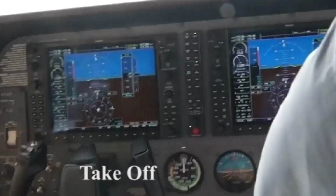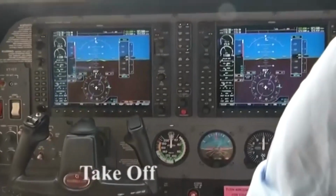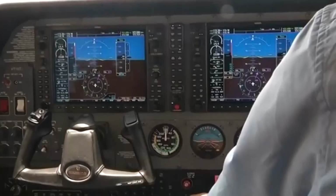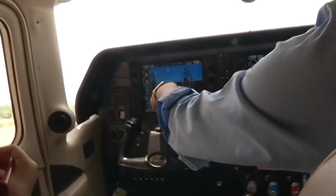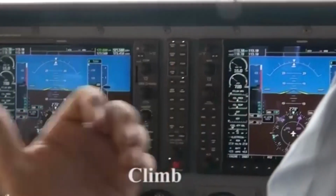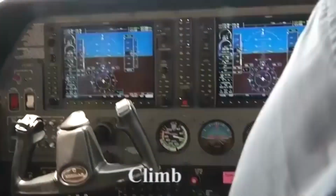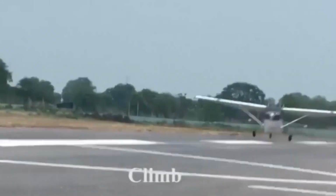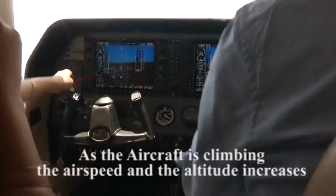Just keep a watch on the ASI and altimeter as we climb. The RPM drop between the two magnetos should be within the limit. Now we can increase our throttle, airspeed alive. After airspeed reaches 60, then slightly backward pressure. Okay, the nose goes up. This is a climbing motion. Okay, airspeed alive. This is the airspeed.